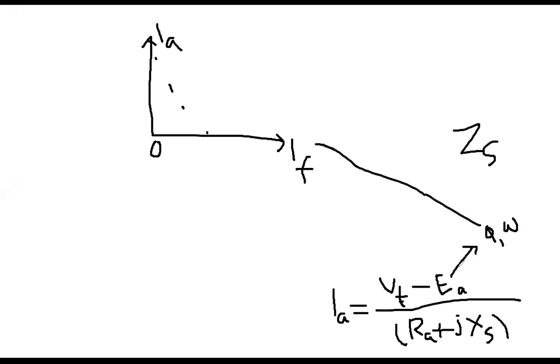And then again, what will happen? Still you are exciting. You are putting in much more field current, or flux. So you will get an increase, and then it goes into the overexcitation mode. Overexcitation mode means you are going into the leading power factor zone. When it was pretty low, and then gradually you are increasing, from the lagging power factor you are going to the leading power factor zone. At this point it is 0, but then again, in the reverse direction, it is increasing.